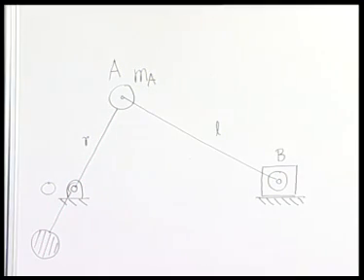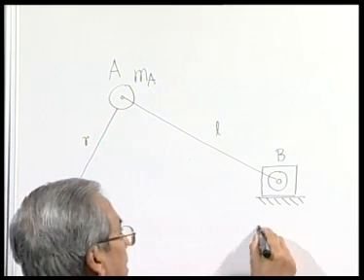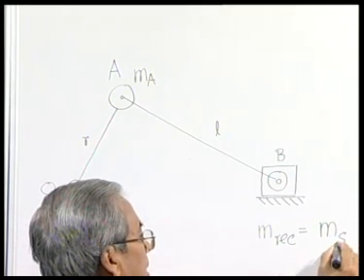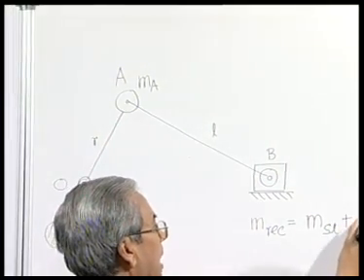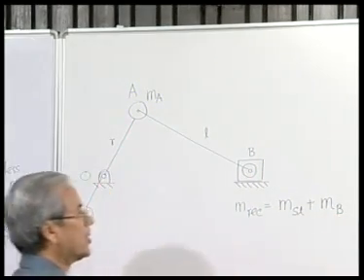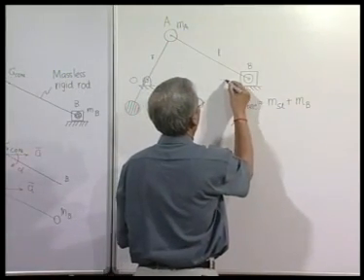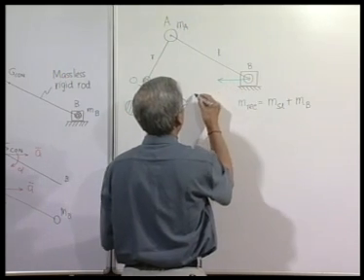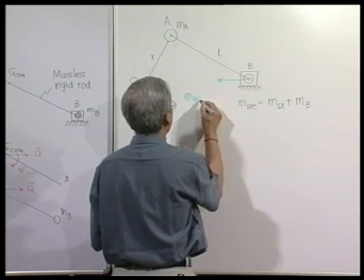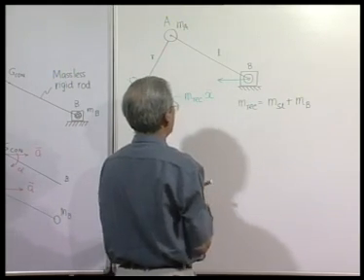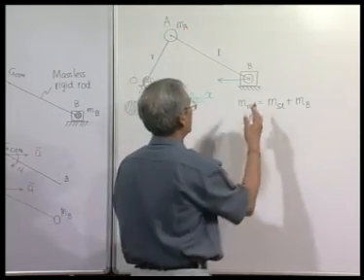So, the only thing that remains that can produce an unbalance effect is this reciprocating mass, M reciprocating, which is the mass of the original slider plus the apportioned mass of the connecting rod at location B. So, now the only unbalanced force will be M reciprocating into minus x 2 dot, where x 2 dot is the acceleration at this instant.